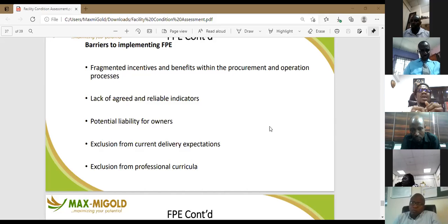If your FCI is very high, it means your repair requirement is very high, which means the higher your FCI, the worse the state of your building, right? So in this case, you've done FCA and you found an FCI that was very small, which means your building is close to new. A building with an FCI of 0.01, that's like 1% of upgrades and repair required to bring it back to brand new. Your building is in top shape.